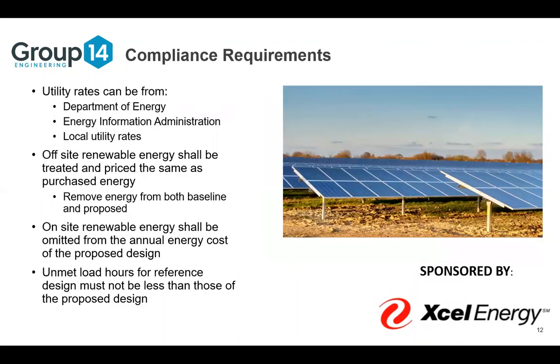Utility rates. So this is a list of compliance requirements that are listed in section C407 of the 2015 IECC. Utility rates can be from the Department of Energy, the EIA's website, or local utility rates. Off-site renewable energy shall be treated and priced the same as purchased energy.